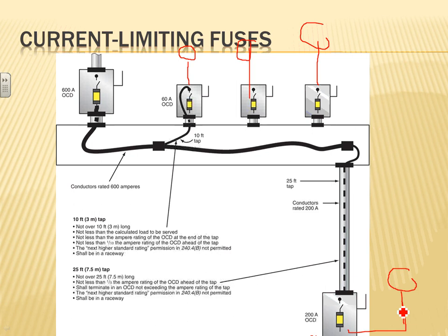Do you use something like this through a gutter? I know as engineers we love to use panels, because panels are great, with every branch circuit directly from a panel. But I've seen a lot of design-build guys who can do things cheaper by utilizing permissions from the NEC code book. That permission is called the 10-foot rule and the 25-foot rule. May I ask, do you guys use this? Dave, do you use the 10-foot rule, the 25-foot rule?